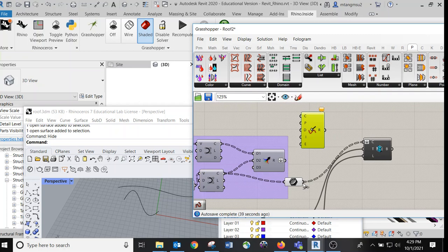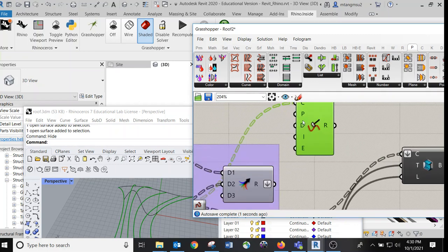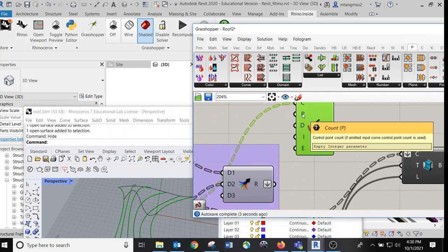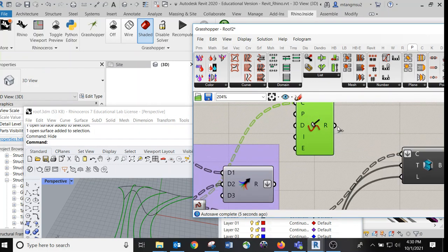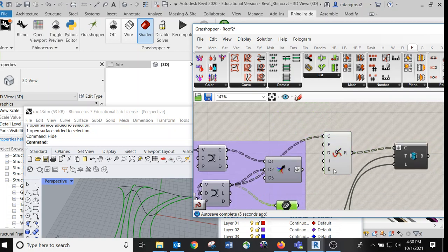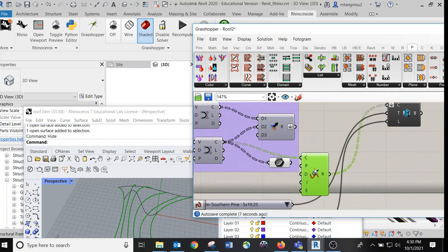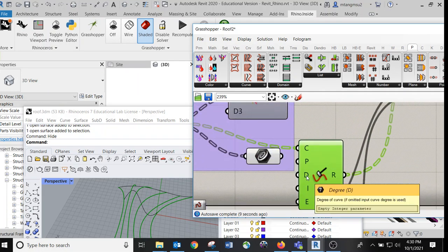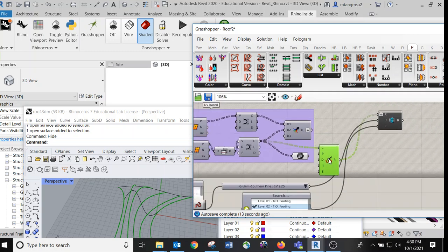This is actually pretty cool. You can take a sequence of curves in, right? It will basically recompute the curve, make it rebuild, and this curve will be cleaned in certain ways. So you can control the degree, you can control the tangent, but in general, by default, if you just rebuild the three-dimension curve, you can tweak.